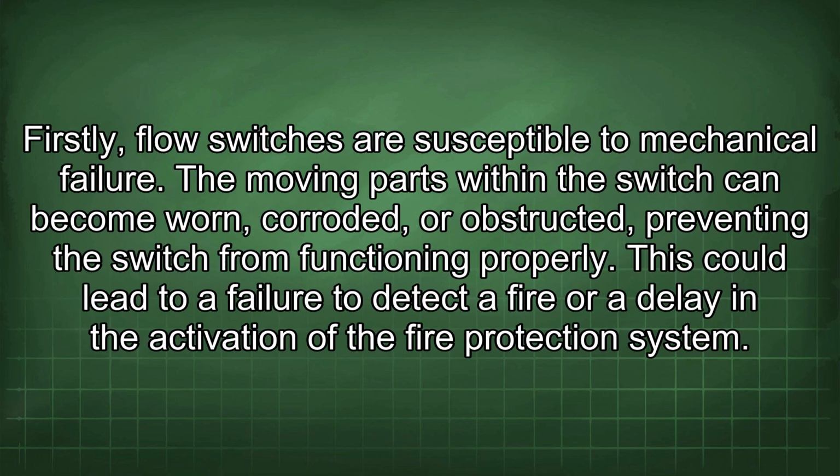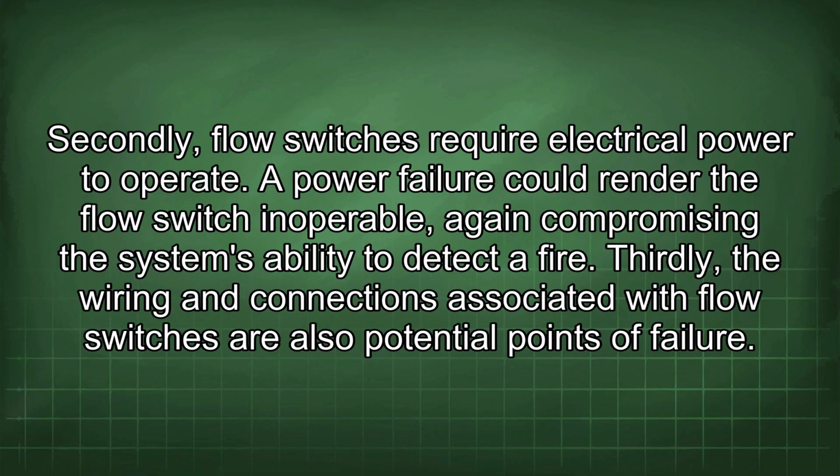Firstly, flow switches are susceptible to mechanical failure. The moving parts within the switch can become worn, corroded, or obstructed, preventing the switch from functioning properly. This could lead to a failure to detect a fire, or a delay in the activation of the fire protection system. Secondly, flow switches require electrical power to operate. A power failure could render the flow switch inoperable, again compromising the system's ability to detect a fire.